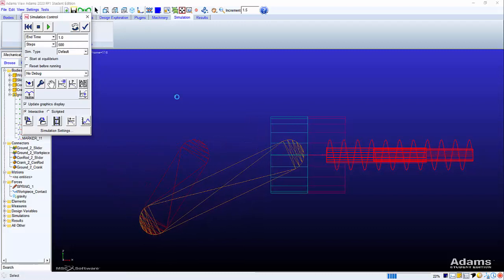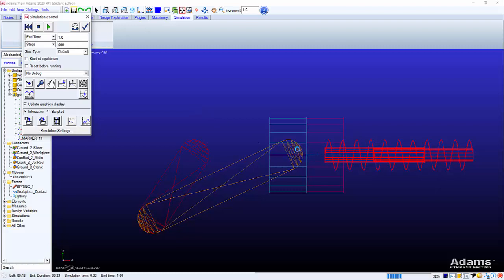Yeah, now it is oscillating a little bit, which is acceptable now. So now it stopped, almost stopped. No more motion. This is what we expect. Now, how is the crank slider going to make a complete rotation? In order to have complete rotations and continuous operation, we need to add a motor to drive this crank slider mechanism. How do we add a motor?